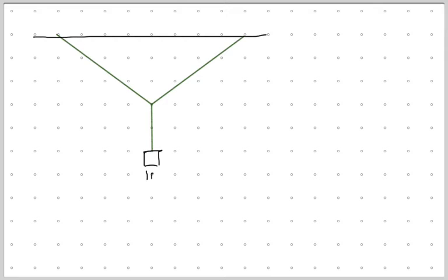It's again static equilibrium. We've done this so many times. This kind, where you have a mass supported. This is one of the easiest things, actually. You have a mass, 10 kilograms or whatever, supported by 3 strings, knotted here. The angles θ1 and θ2 are given. You should be able to calculate the tension in the two parts.